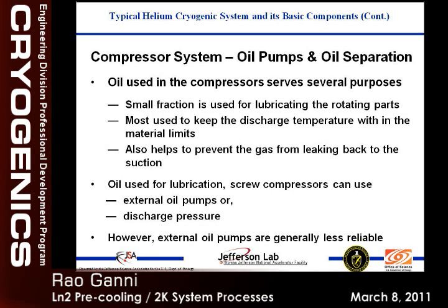Also, it provides a good seal on the rotor so that there's no blowback, and improves the volumetric efficiency. And it lubricates. And there are two ways. One is external pumps are used to provide all this oil, or you can use the discharge pressure to circulate the cooling oil, and only use the pump for lubrication of bearings and the slide valve. So, yeah. What kind of oil is it?